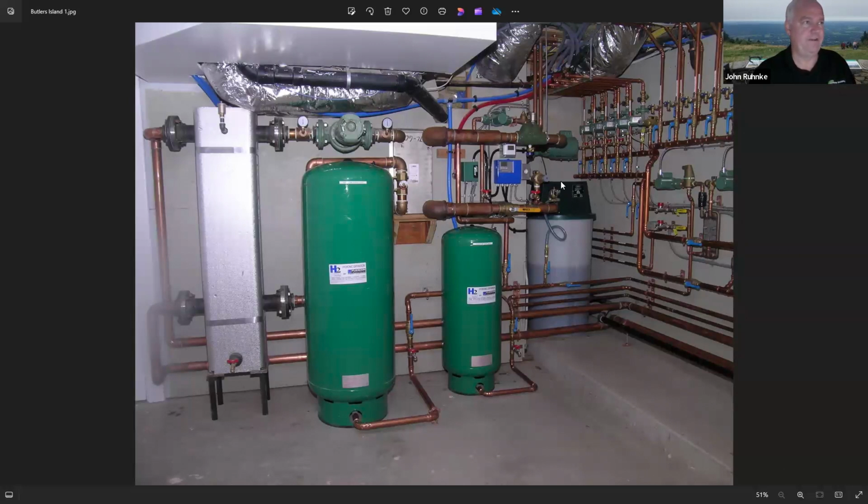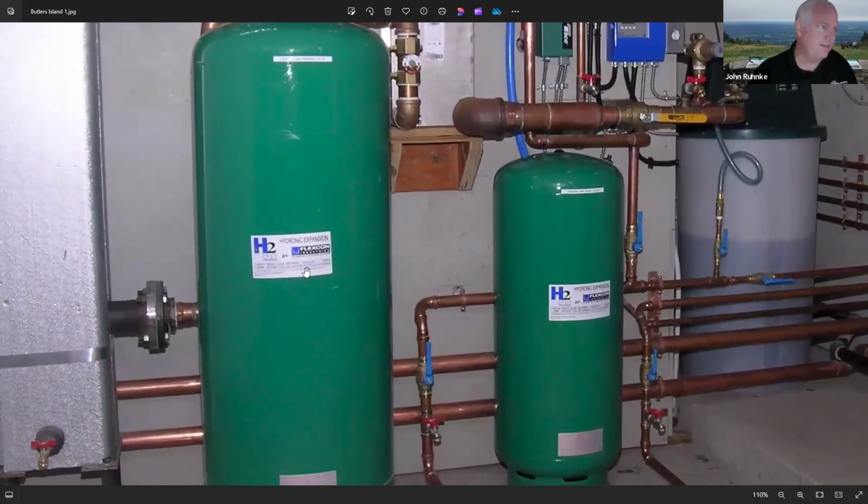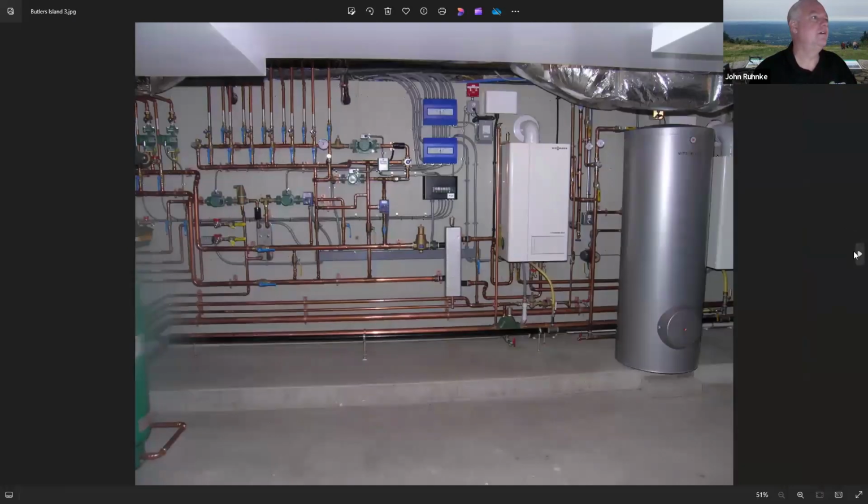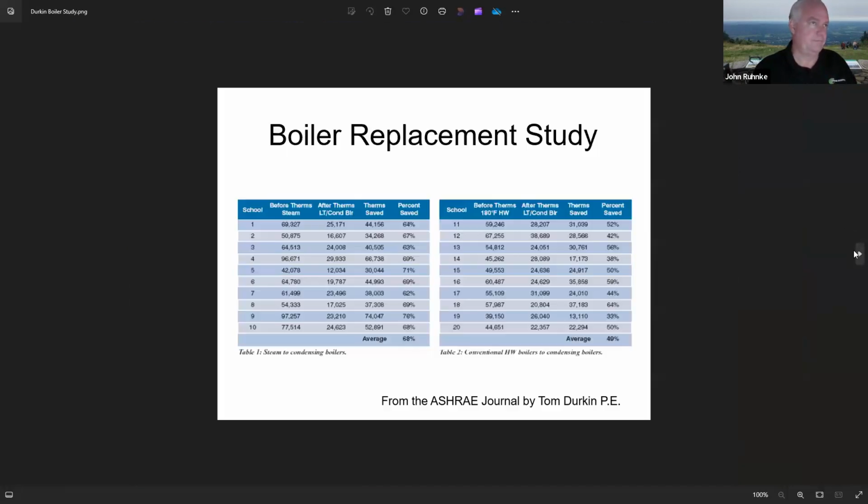And then this is a feeder that feeds antifreeze into the system. So this is all water on this side, and this is antifreeze on this side. And this is just an expansion tank. That's all this is. Basically, as the water gets hotter, it grows. And then there's a bladder in here, and it pushes against the bladder, so it compresses the air. Without it, you'd pop the relief valve because the water would grow. It needs a place to expand into. So that's what this tank is. It's just an expansion tank. Thanks.